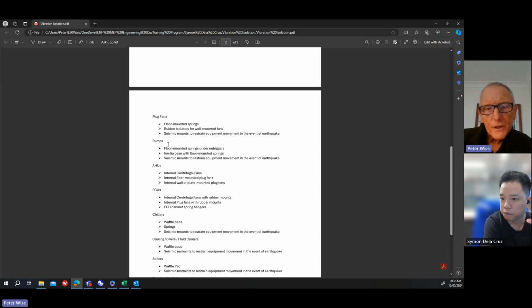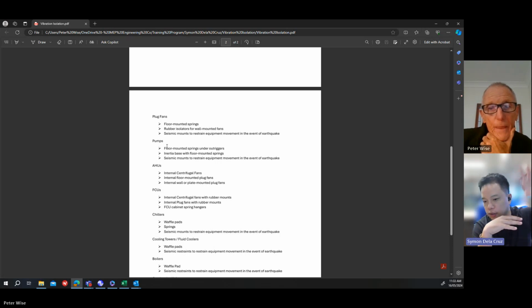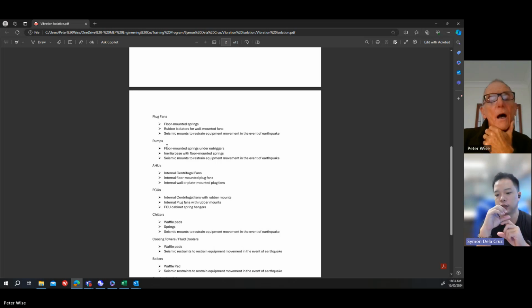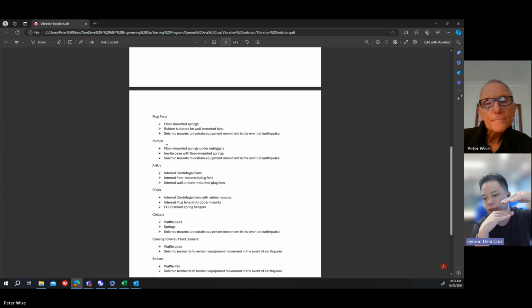So what was the situation again? You've got a discharge duct. Yep, if we have equipment, like an AHU with a vertical discharge ductwork, with this spring. Do we need to know already the spring height so that we could assume the length? Because it will affect the length if we don't assume correctly those spring mounts.